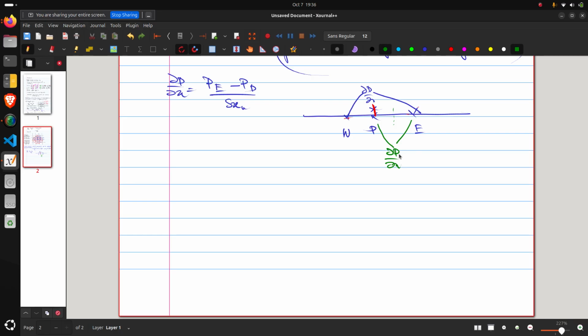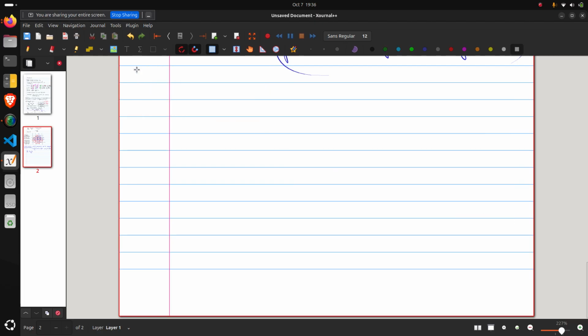Okay, so let me just give you a demonstration of how this kind of checkerboarding or staggered grid comes into the picture while solving the momentum equation. As you all must be familiar with, we will have a form like a_P u_P equals the summation of a_nb u_nb, minus that pressure gradient term, dP/dx times delta V, which will also be there because it is integration over the control volume, plus some source, right?